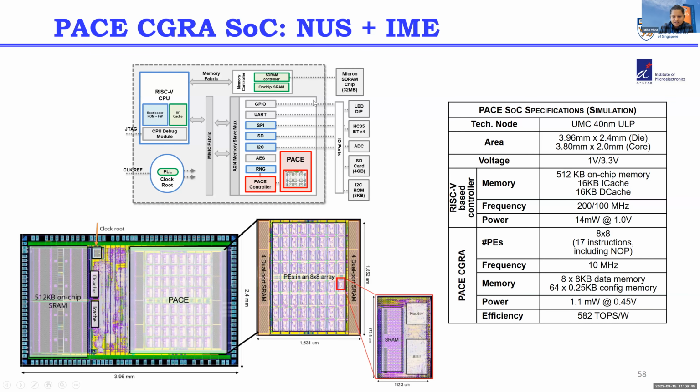So into the details of the architecture, if you see the layout, there is an external SDRAM memory, and there's some on-chip SRAM as well. So in the fabric, the majority of the portion is taken by the SRAM as usual. And apart from that, half of it is the base core, in which you have the dual port memories on the sides. And in the PE array, you can see there's also a local memory, which is the configuration memory, and router and ALU.